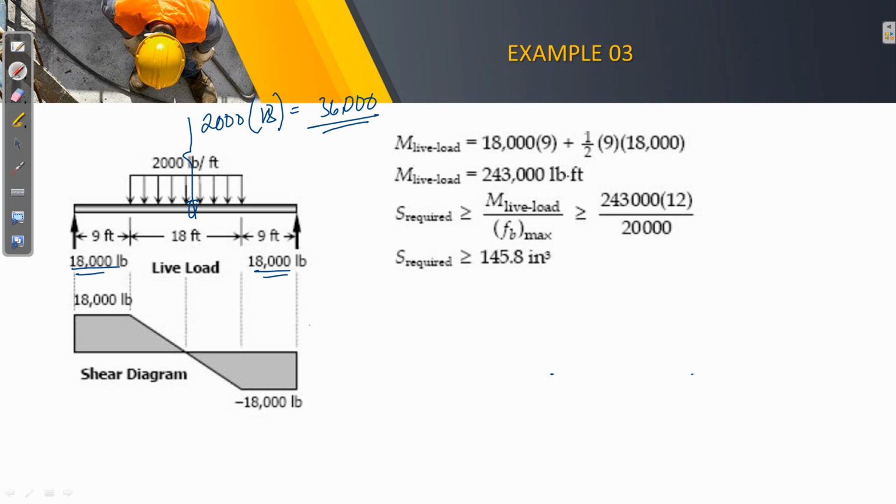So from that, anyway, these shapes are equal. We have a positive and a negative area. So by symmetry, your moment diagram will just close because you have an equal positive area. And your maximum moment will surely occur at the point where the shear intersects the 0 line.